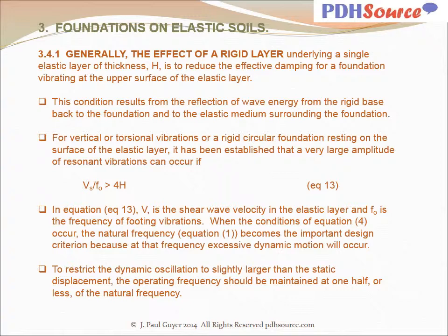For vertical or torsional vibrations of a rigid circular foundation resting on the surface of the elastic layer, it has been established that a very large amplitude of resonant vibrations can occur if V_s divided by f_o is greater than 4H. Equation 13 on slide 21.